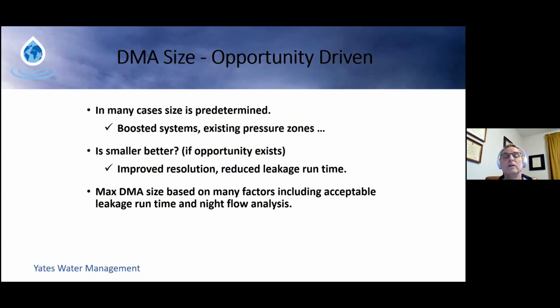And as it comes to town, it of course increases in pressure, and we have to intentionally reduce pressure before it reaches the customer. But in some cases, because it's hilly, we may pressure reduce in some areas, but there's other areas, just like I showed you, where we had to boost as well. So these are automatically a great candidate for DMA, okay? Because they're already set up with isolation valves, isolated from other parts of the system. And that's key to DMAs. You must isolate so it truly is standing on its own in terms of water flowing in and water flowing out.